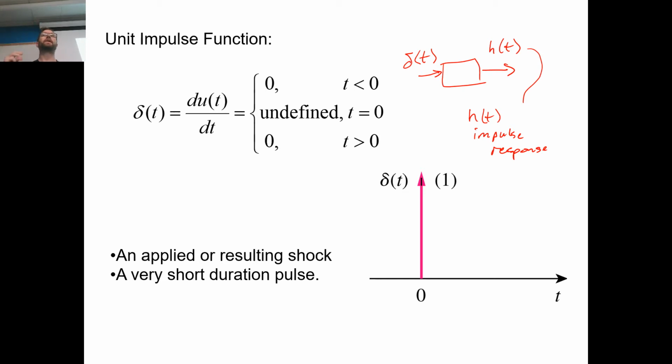Going back to that example of walking into a cathedral or a church and snapping your fingers, what you're listening to when you hear that is the acoustic impulse response of that system. And if you were to measure that with a microphone, it turns out that once you know how a system responds to an impulse, you can estimate, in fact with great precision, and in certain circumstances exactly calculate, how it will respond to any signal, no matter what it is.